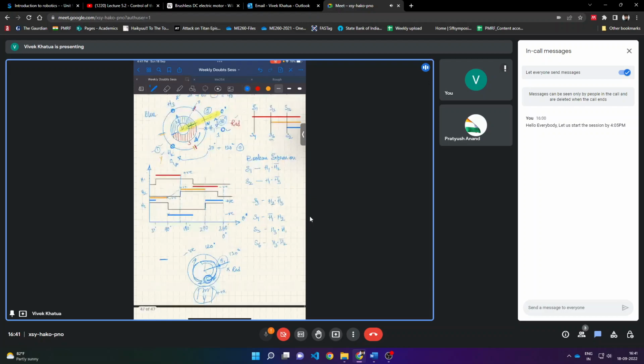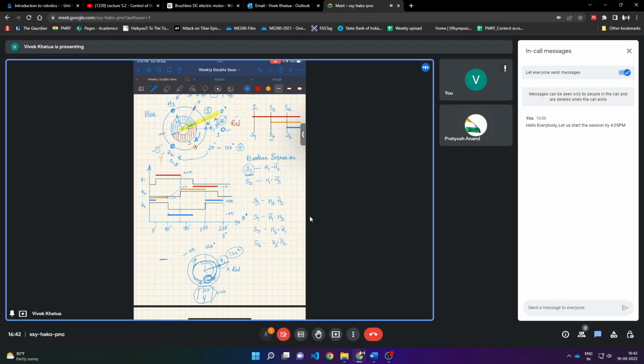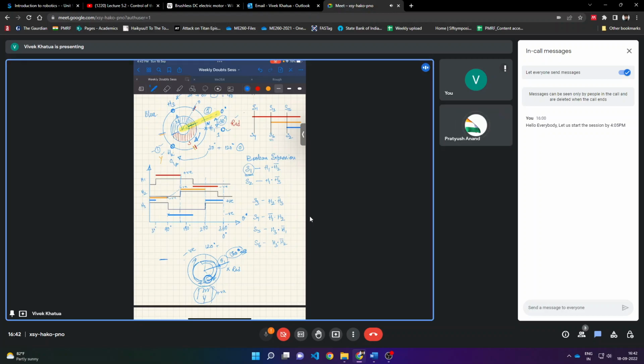So if I have to come to a Boolean expression without looking at the H1, H2, H3 logic, how I can think of it is that my switch 1 should be active till this 120 degrees. Actually this is 150, since 30 plus 120.